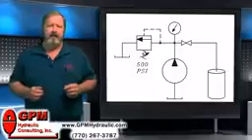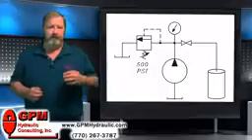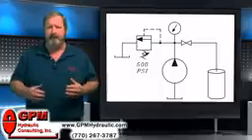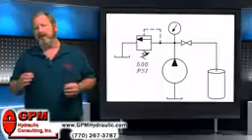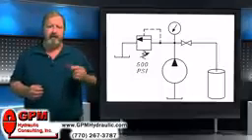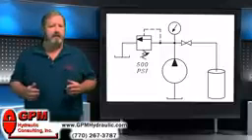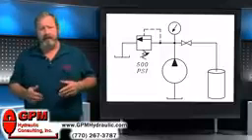Most people think that the pump pumps the pressure. In other words, that's where the pressure comes from. It comes from the pump. And if the system pressure is lower than it should be, the problem is probably the pump. This is not true. The pump doesn't pump pressure.